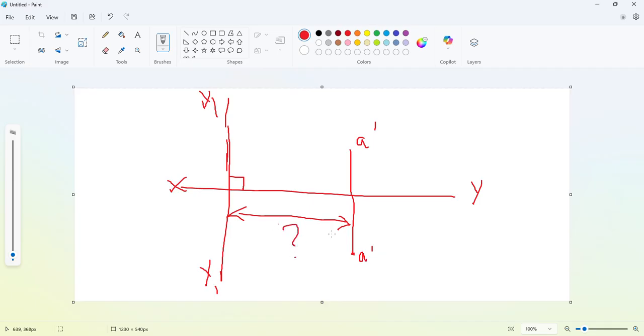If not, here I'm just giving an example, so without any distance, I'm just taking a reference line here. If in the question the distance is given, you can take this reference line at the same distance from the projection point. If it is given 20 mm from RPP, you have to take 20 mm from the projection on the left side.